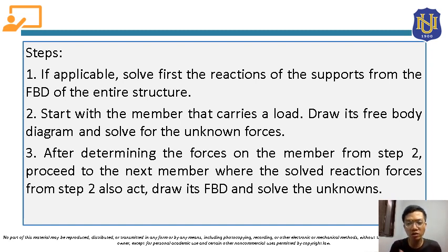So the reaction forces that we solve from step 2, from that member, we are going to use that in solving for the unknown forces in the free body diagram of another member. Again, we are going to use that principle that if we transfer a reaction force from one free body diagram to another free body diagram, it should be directed oppositely. So we have to be consistent with that.